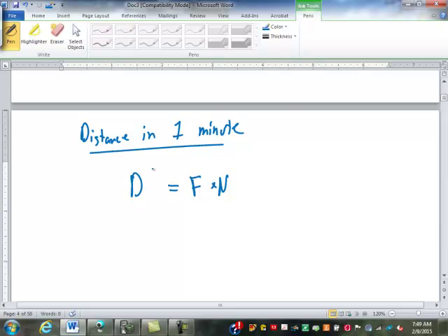So that's your distance. Well, the time it takes would be the length of that cut divided by how far you would move in a minute. The time in minutes, of course, we're looking at. Be the length of that cut divided by that feed times the RPM.